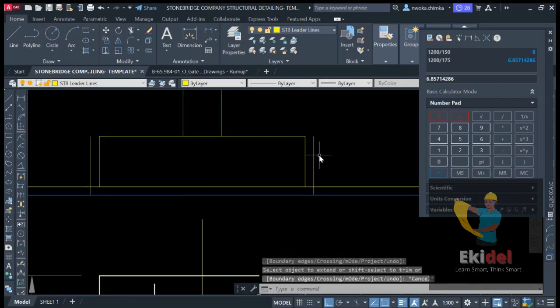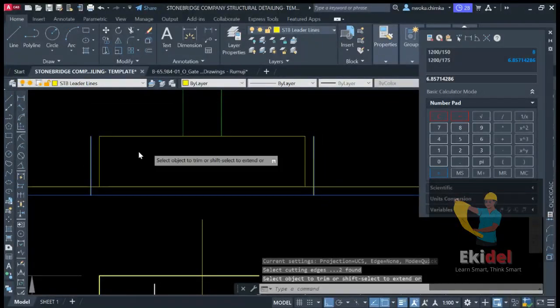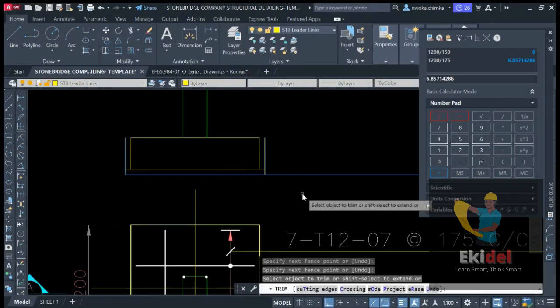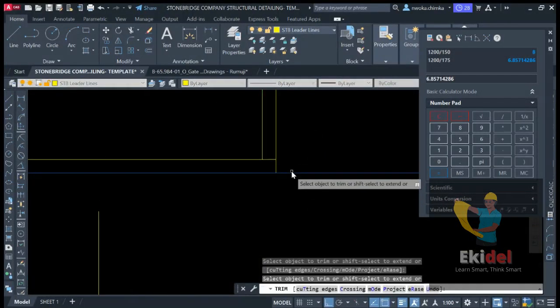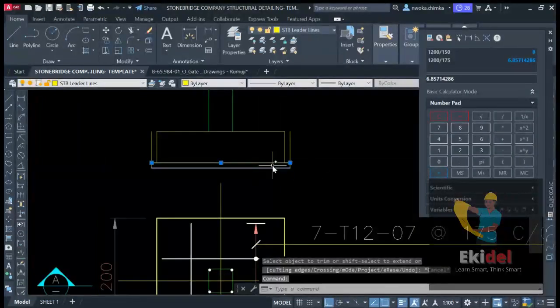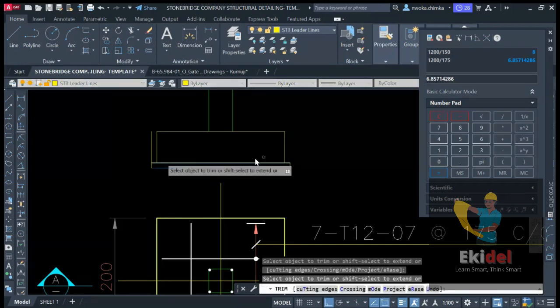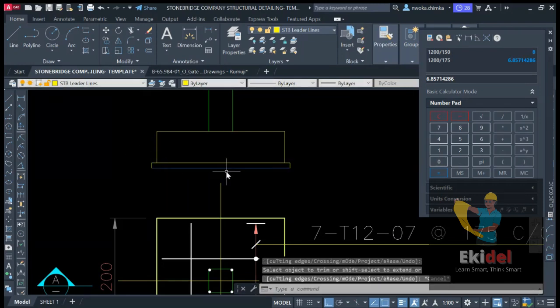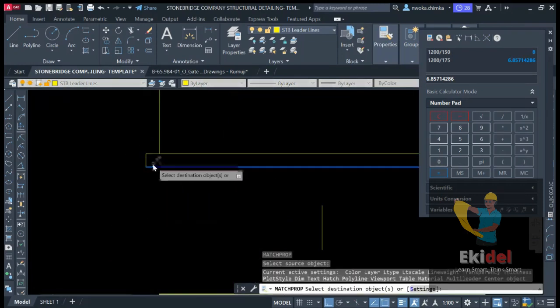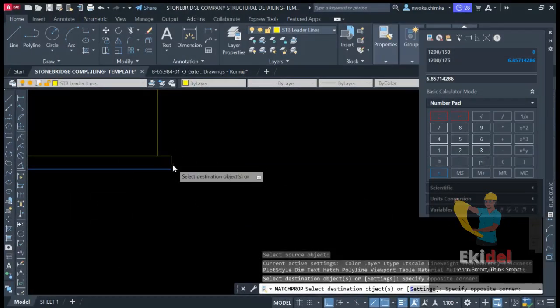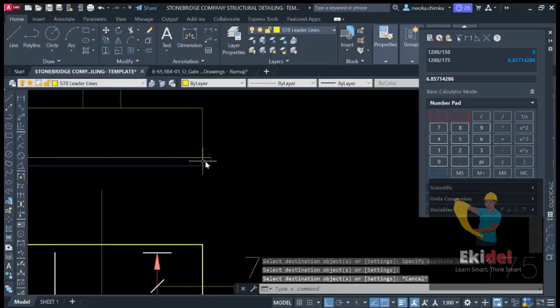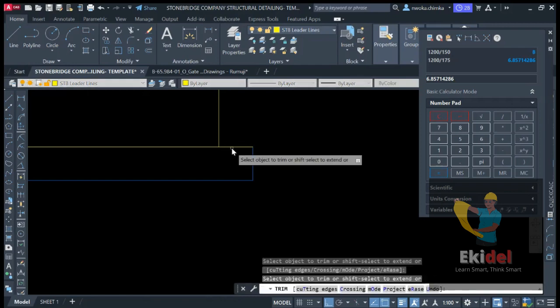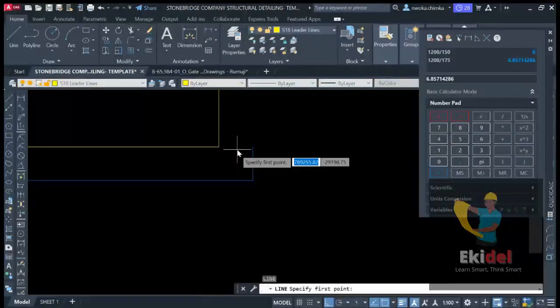And then I will click on these two and these two, and then trim off this, and trim off this also, and the same thing, trim off this also, and then hold here, and then trim off this excessive one here, and also this also, and then change this to blinding color, and here blinding color also, and then just trim off this now because here has to also be a blinding layer.